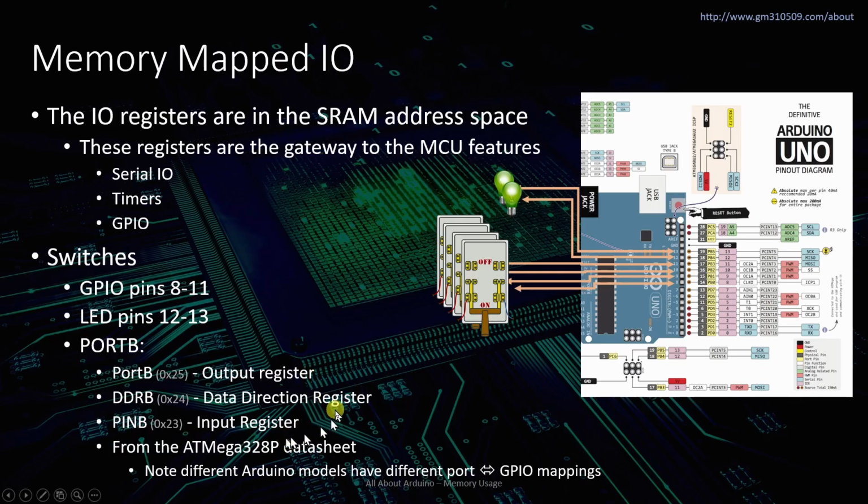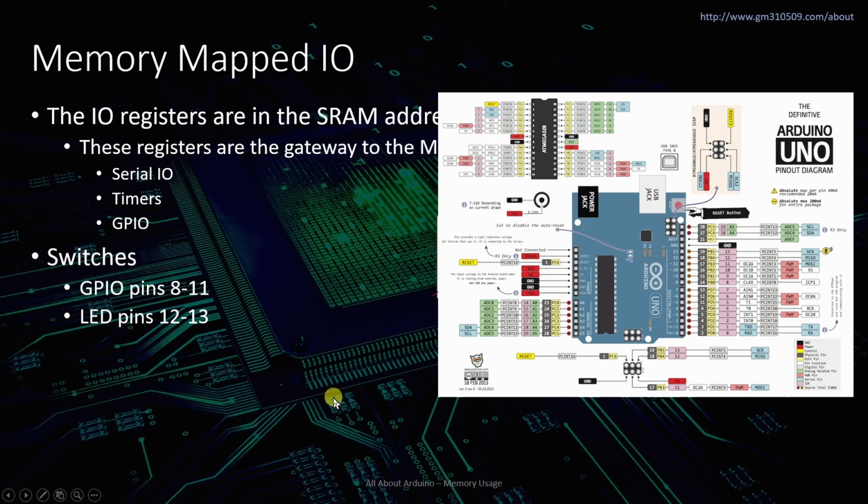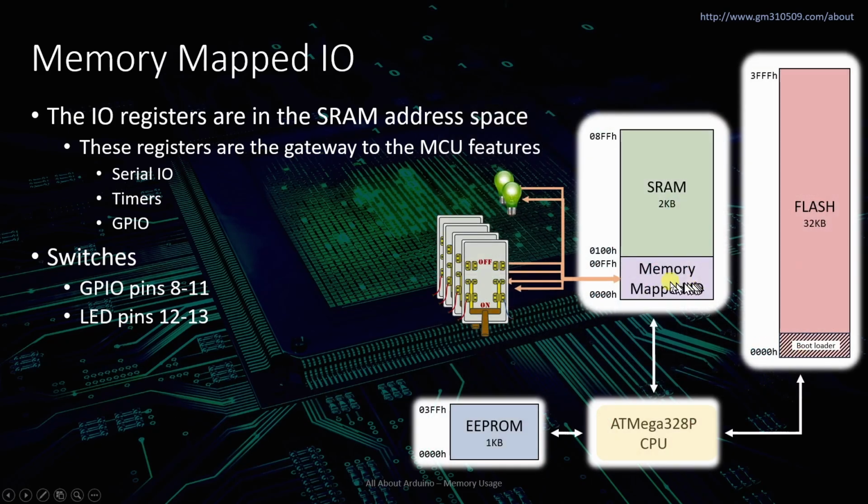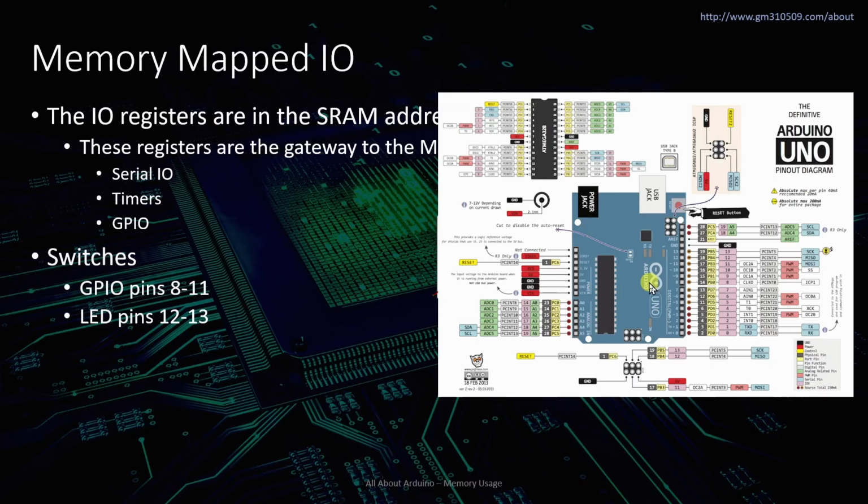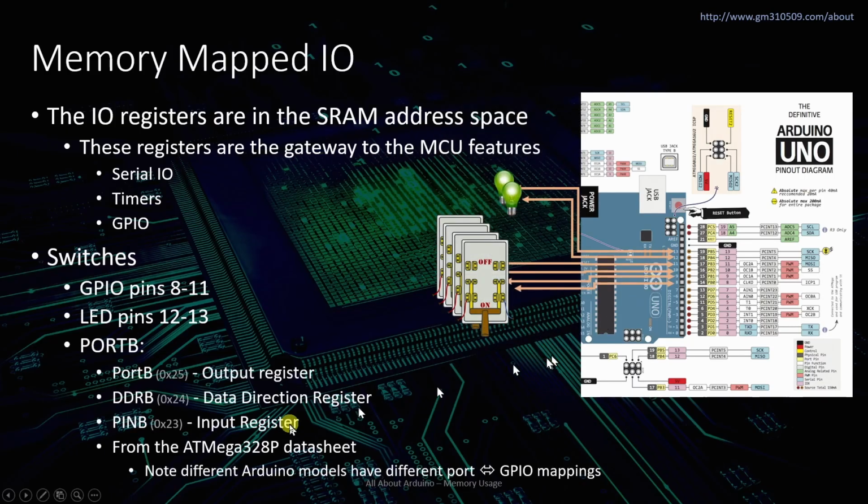And those descriptions are generally what they do, but there's a little bit more to them, and they do have extra capabilities depending upon what mode they're in. And these numbers here, 23, 4 and 5, are the addresses in memory. So that's the address of port B in this memory mapped I/O here.